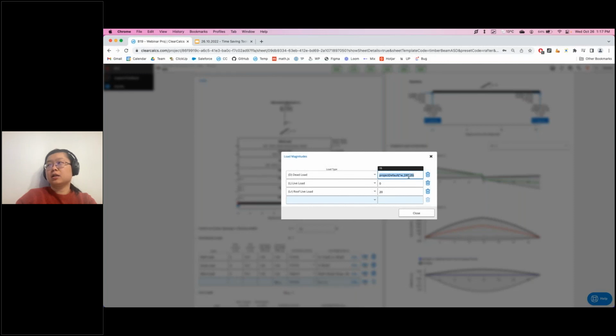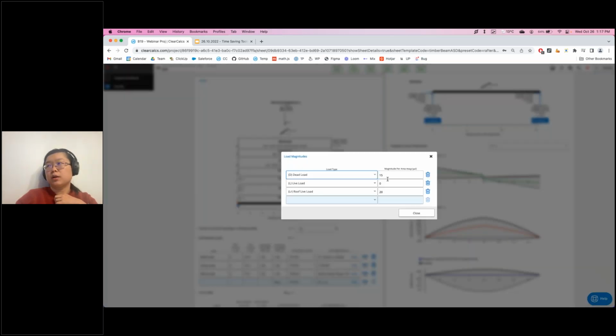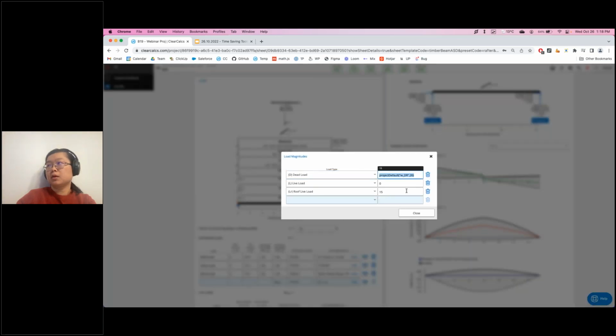And this is usually the minimum. So if this number, like WDR, is not defined, we'll just by default put in 20. So it's the minimum, sorry, not the minimum. We pull in this number first, and then if this number doesn't exist, we'll pull in 20. And actually that's why you'll find if you start a generic beam, we'll start with 20 and 40. And so these formulas are all here for your reference. So actually, if we want to set WDR, this should now also reference 15. Does this help?